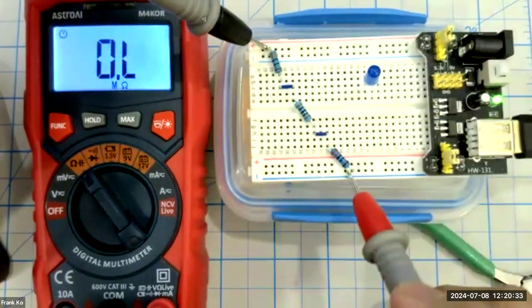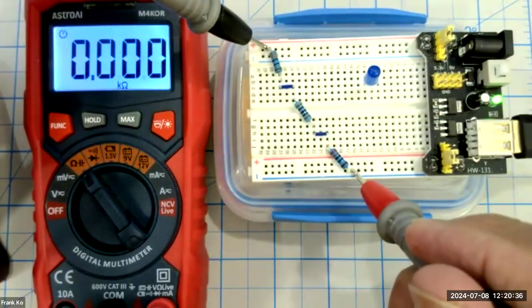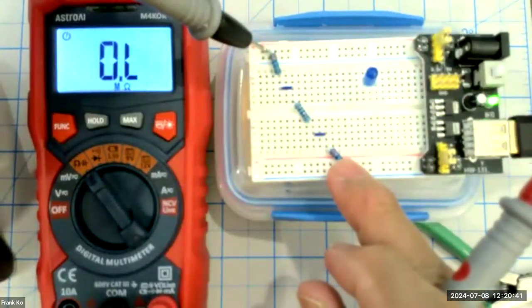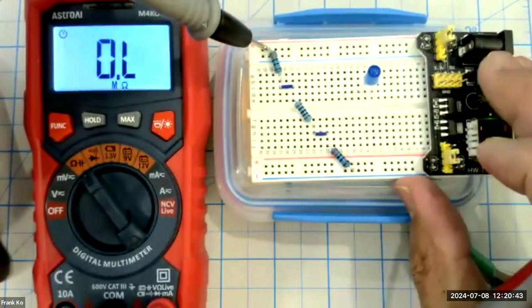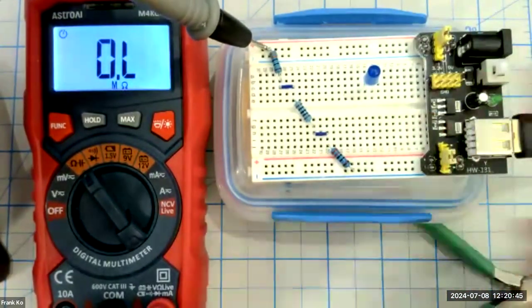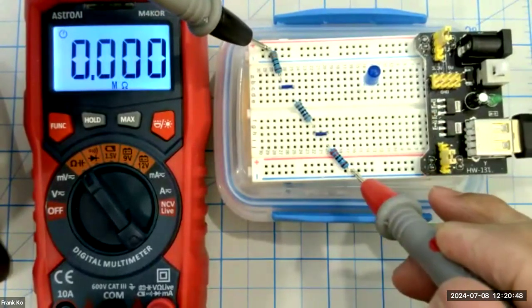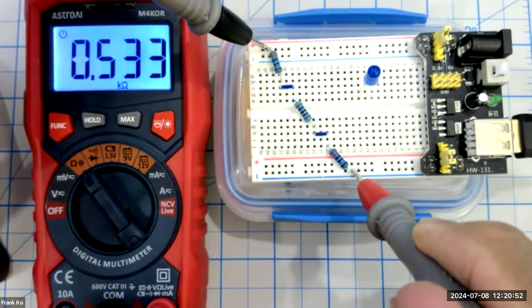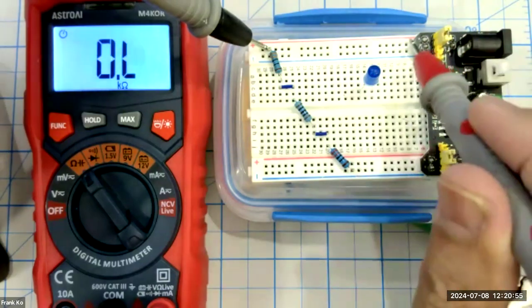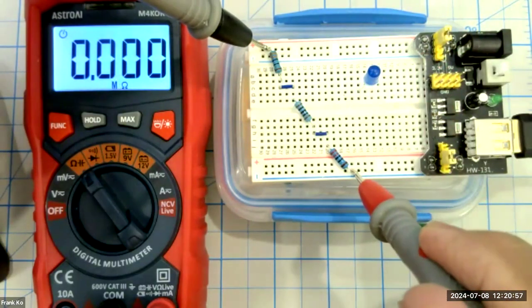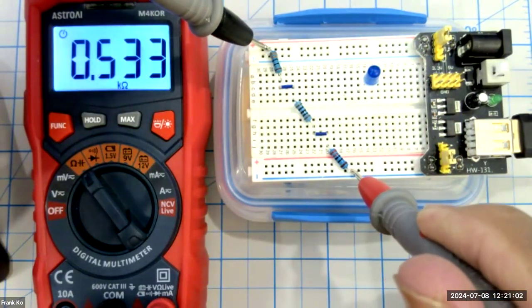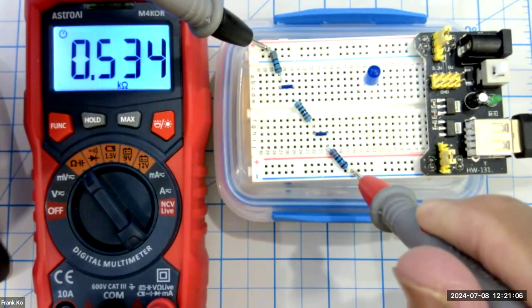You turn it on, and then for sure, you're not going to get any ohms because resistance cannot be measured while electricity is flowing. So you figure, okay, I'll turn it off, and therefore, if it's not on, it should not affect my total resistance. And yes, it does, because there's circuitry in your power supply, and that power supply being hooked up on the positive rail and the negative rail, guess what, friends? It's going to mess up your total ohms. We are nowhere near the total ohms that we expect to be at 650. We're 534. So what do we do?